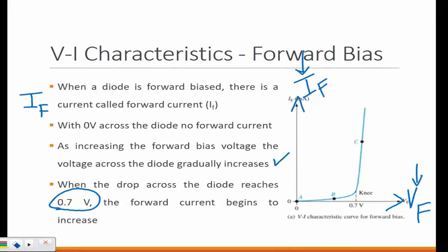As you can see, below 0.7, the current is extremely small and gradually increasing. But once you hit that 0.7, you see the current curve drastically increasing to whatever the circuit capability is. Based upon the voltage source and the resistance we are providing, the current will drastically increase once the voltage on the diode, again, it's not your source voltage, closes that barrier potential.